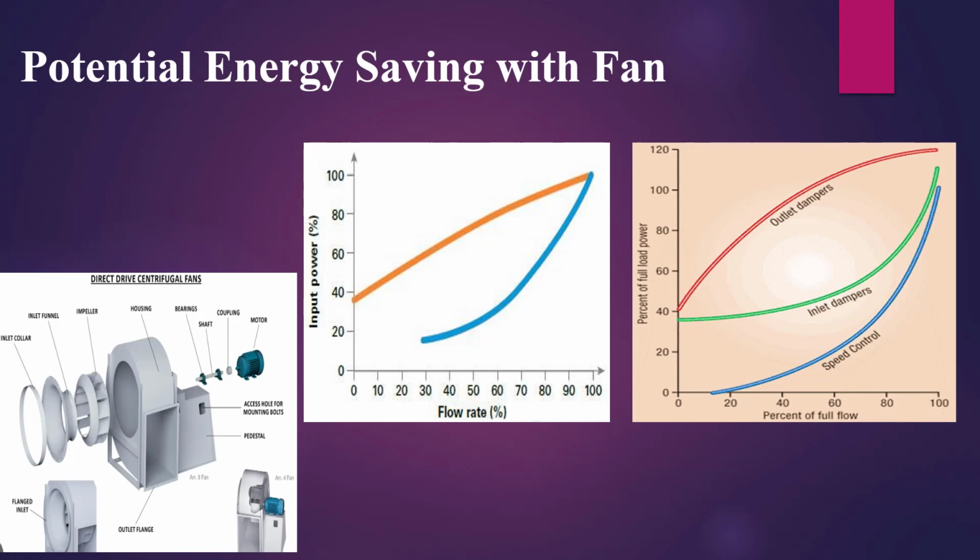If the damper is replaced by a variable speed drive, airflow information is used to adjust the motor to the right speed. When the fan speed varies, power increases proportionally to the square of airflow. For 80% airflow, the motor operates at only 50% of its power. This means power consumption is halved by the use of a variable speed drive compared to a damper solution.